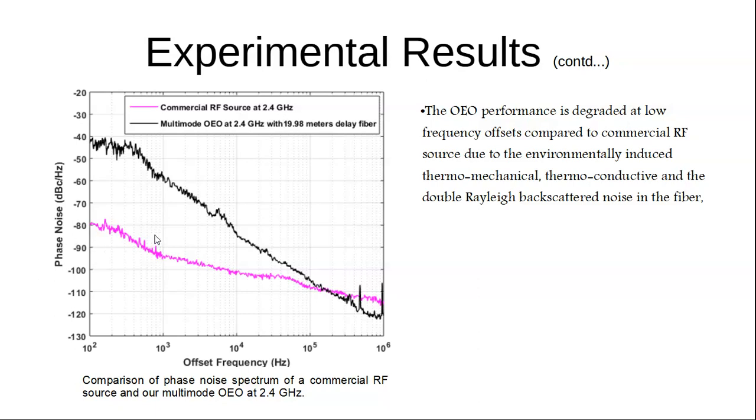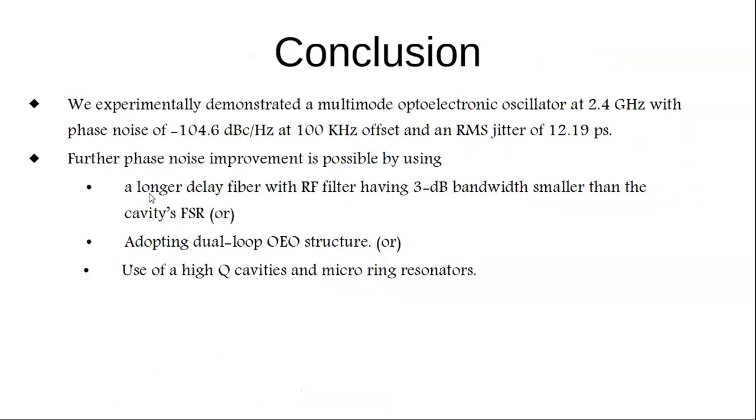As you can see, our OEO performance degraded at low frequency offset compared to the commercial RF source due to environmentally induced thermomechanical, thermoconductive, and double Rayleigh backscatter noise in the fiber.